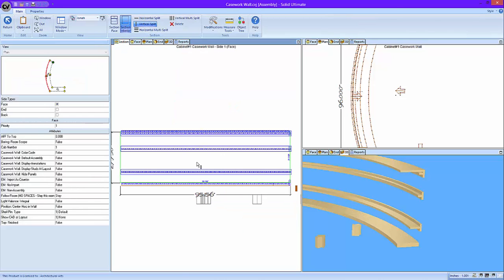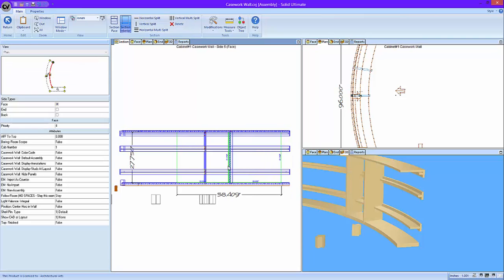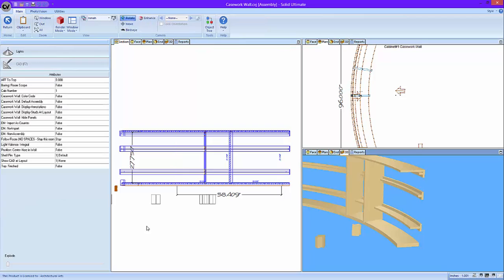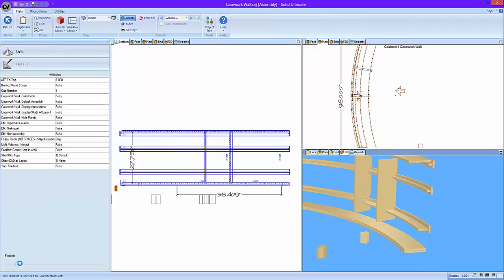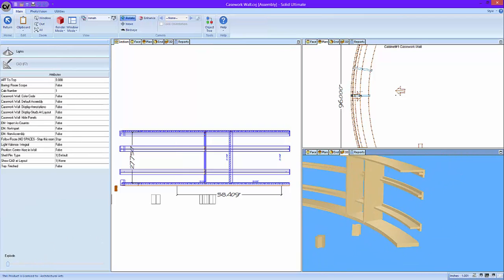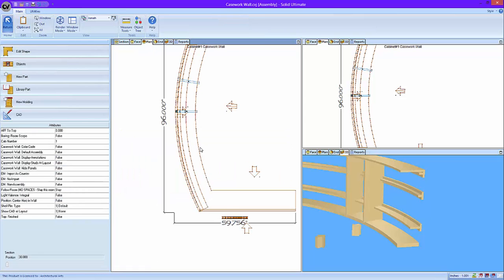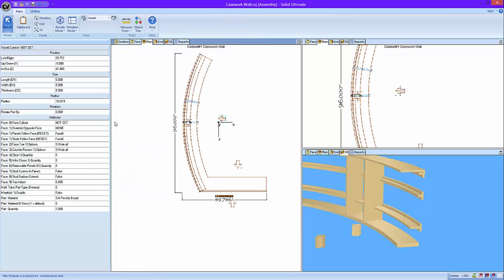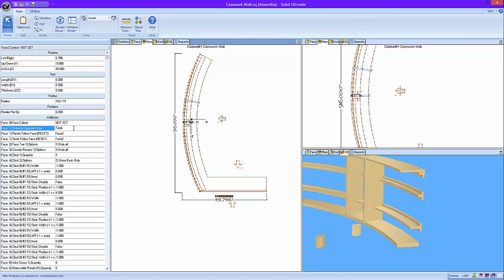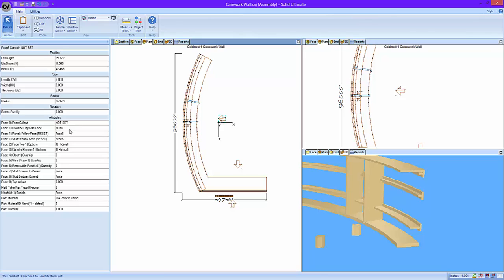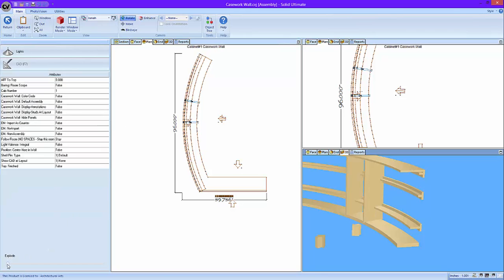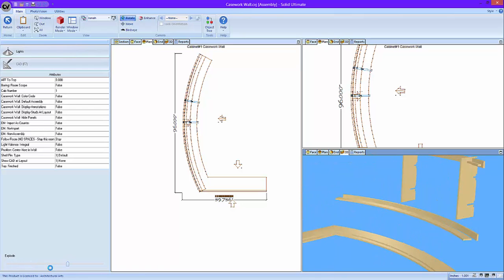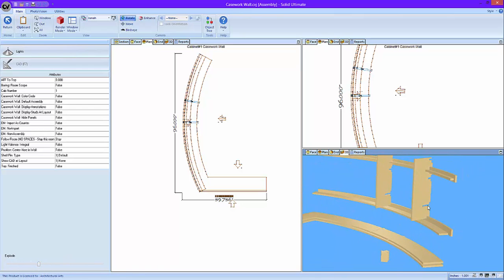Studs work the same way. You can put them in from either face. And it looks to the opposite faces. Sometimes it fails to detect the other face, so we have to tell it what it is. The opposite face of this is face 6. The opposite face of this is face 2. This only happens with radiuses. Now we'll pull it apart. You see, you end up with a stud with a notch out like this.